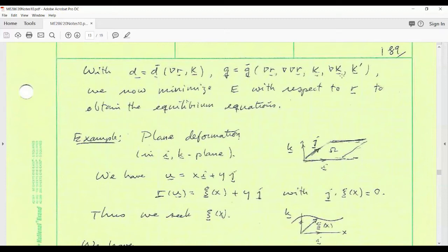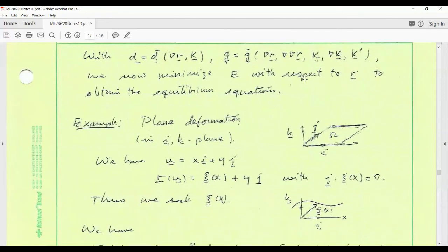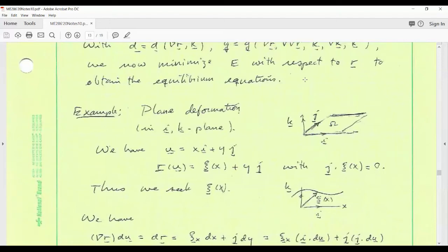But the great gain that we've made in doing that is that we're now solving everything on a 2-dimensional domain instead of 3D. That's far simpler. So we accept the extra complication because the analytical aspects of the theory are much simpler on the 2-dimensional domain. That's the same as in ordinary beam theory, right? In ordinary beam theory, the strain energy of the beam depends on the curvature of the center line, which involves a second order derivative of the deformation of the center line instead of just a first order derivative. So in structural mechanics, we're accustomed to this kind of thing.